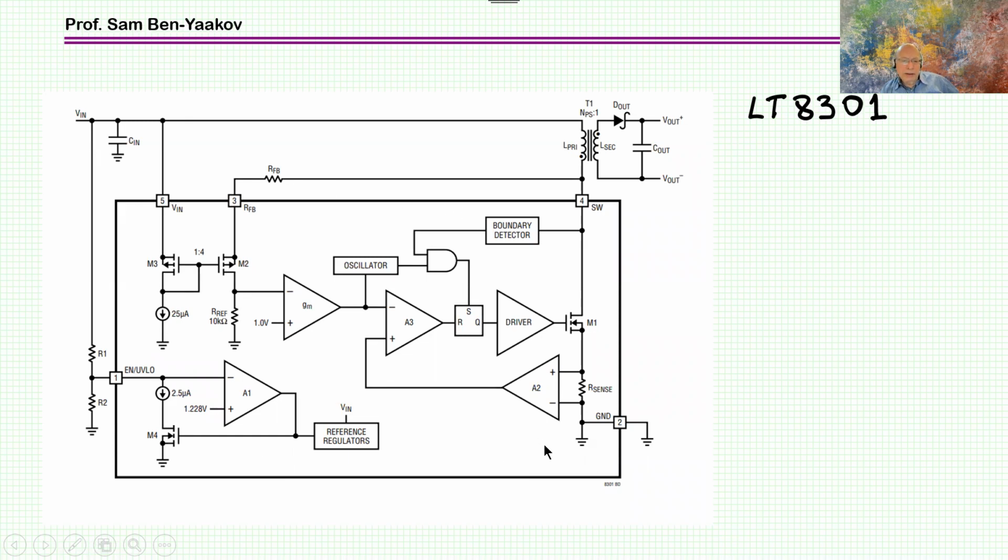By the way, this particular unit is working with the so-called primary side control. It's very tricky. Rather than measuring the voltage at the output to stabilize it, it is measuring the voltage at the primary, the reflected voltage, which turns out to be during the off time, and it's sensing it in a clever way so that you don't have to have a feedback from the isolated side, which is very nice.